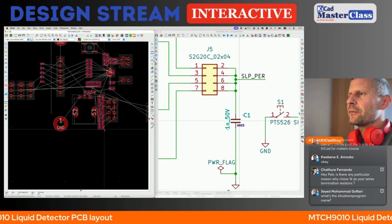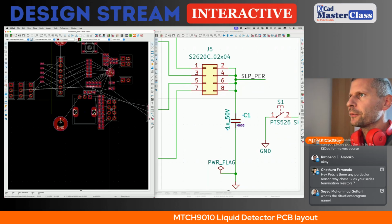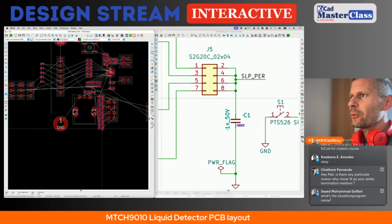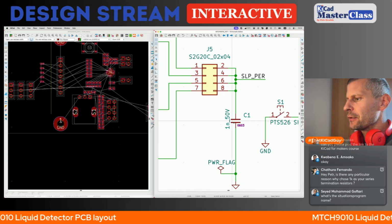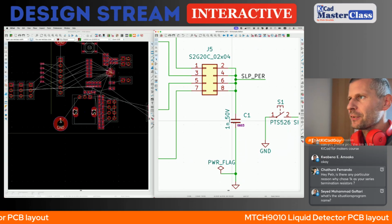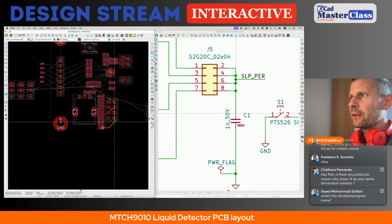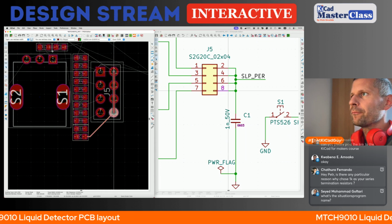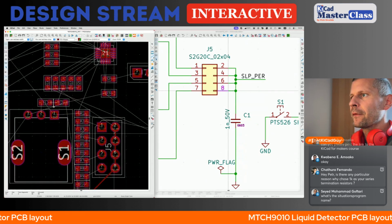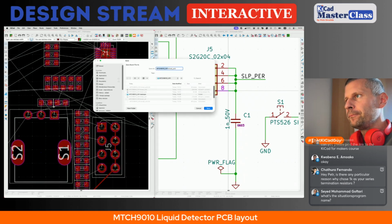Oh, the capacitor ideally should be closer to the IC entry point, because it's the RC low pass filter capacitor, and this is quite a long track from here to here.